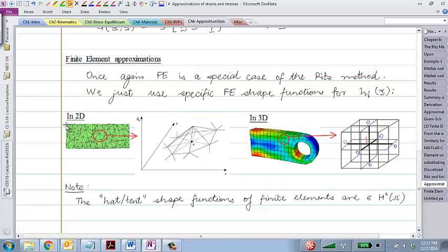We can simply go to those nodes and say that the x displacement of those nodes has to be 0. If I do that, then you can imagine that the entire edge would go to 0, right? If the displacement in the x direction of this node and this node is 0, then this entire edge has displacement equal to 0.